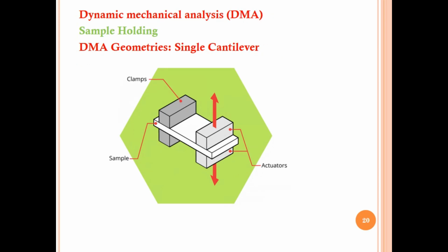There is also a single cantilever used for sample holding in DMA analysis. The single cantilever geometry is presented in this figure. Again, there are the actuator, clamps, and the sample, which is held between the clamps and the actuator.